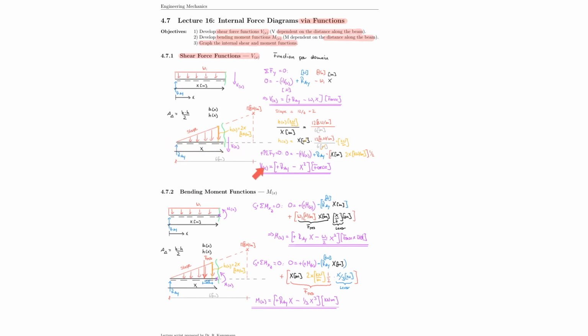This function, the shear force, and the moment function is really true for x equals 0 to wherever this point here is. And then after that, something else happens, and I would have to develop a new function. But you have now all the tools to do that, and in the homework you will be challenged to do this for, I think, up to 3 or 4 domains. So beams have to be broken down in domains first, and then you develop the functions. But I will show this to you now as an example on the following pages. And so let's move on.